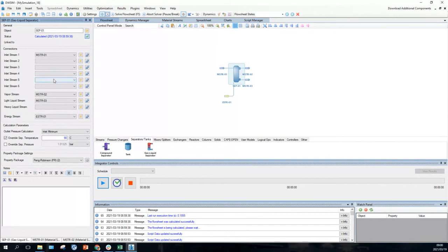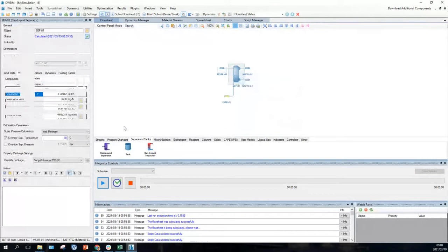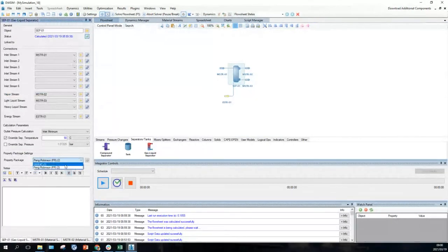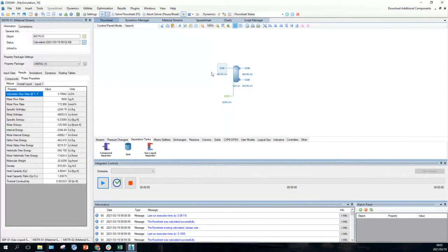Okay, now let's go and have a look at this stream 1, and we're going to change its temperature. Oh, right. Let me go back there and change back to Unifac. Okay. And now we go to stream 1 and we change its temperature to 90 degrees.